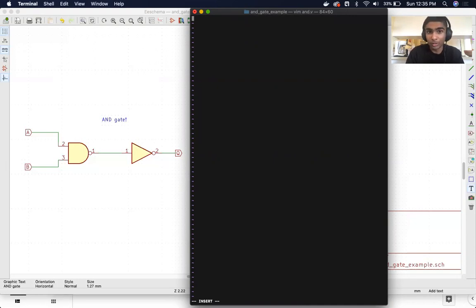I'm going to make the module with our module wrapper. So module, and then let's call it NAND2, because it's a 2-input NAND gate. Stick some parentheses, and then end module. Okay, next, close the parentheses and add a semicolon, and now we can list our inputs and outputs.